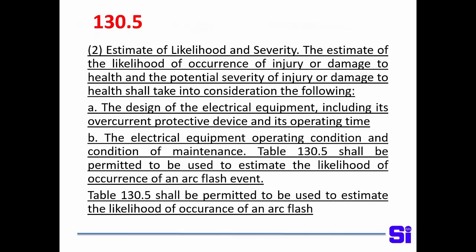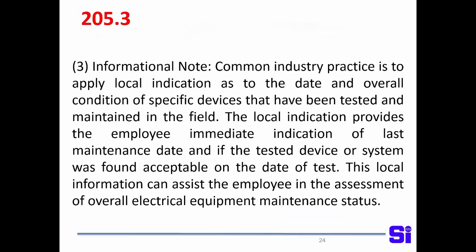And that table did provide some guidance as to the likelihood of the occurrence of an arc flash. By moving it into 130.5 as a standalone table, now you'll be permitted to use that table to estimate the likelihood of an arc flash.